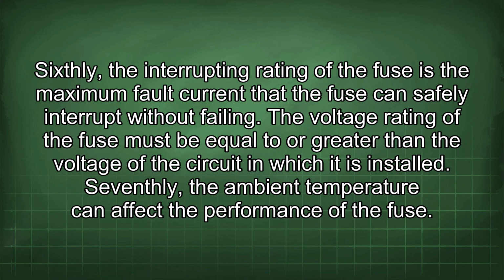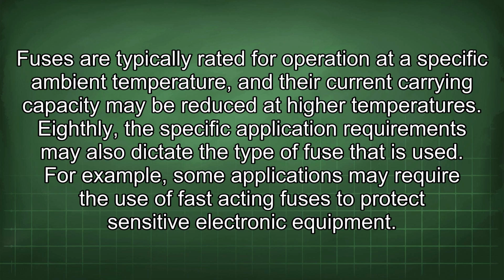The voltage rating of the fuse must be equal to or greater than the voltage of the circuit in which it is installed. Seventhly, the ambient temperature can affect the performance of the fuse. Fuses are typically rated for operation at a specific ambient temperature, and their current carrying capacity may be reduced at higher temperatures. Eighthly, the specific application requirements may also dictate the type of fuse that is used.